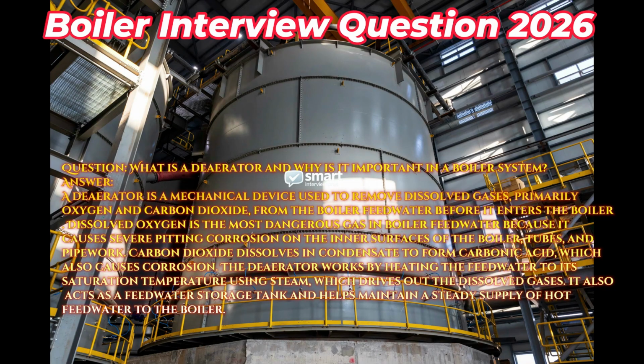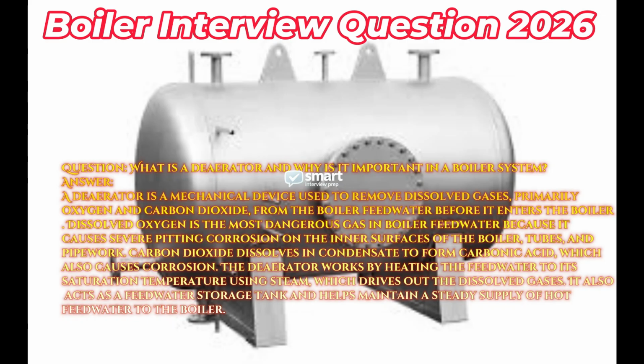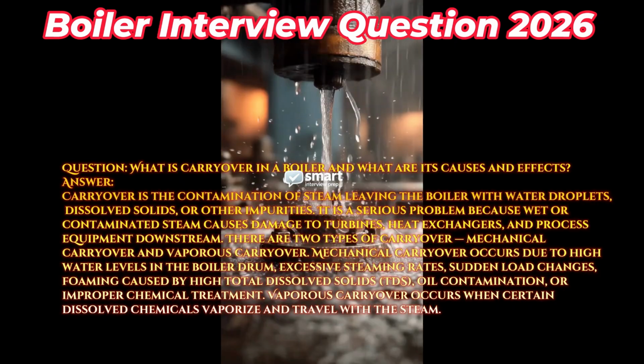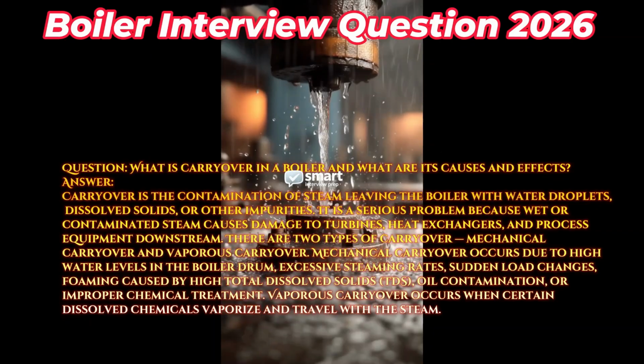Carbon dioxide dissolves in condensate to form carbonic acid, which also causes corrosion. The deaerator works by heating the feed water to its saturation temperature using steam, which drives out the dissolved gases. It also acts as a feed water storage tank and helps maintain a steady supply of hot feed water to the boiler.